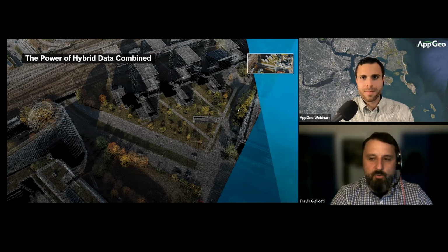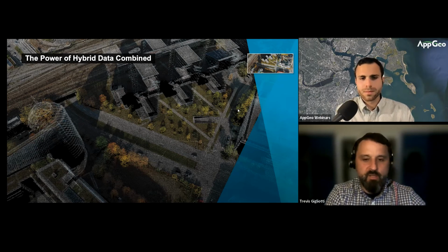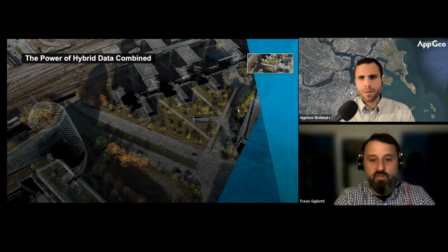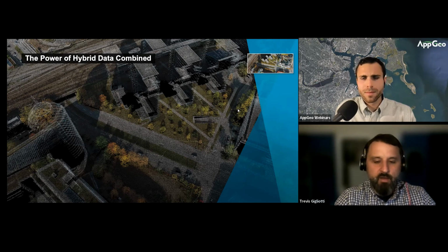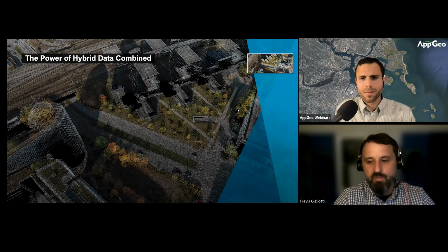In addition to the spectral encoding, we offer this with standard LiDAR intensities. This data product can be further classified as per ASPRS standards or classes. Out of it can be derived further products, such as our DSM, which we'll show in a second, and also DEM as well. This is also high density LiDAR data. We're trying to collect 20 points per square meter on the acquisition side. We don't always achieve that, but that's certainly our target. So we're in the 15 to 20 points per square meter range, which is extremely high density LiDAR.